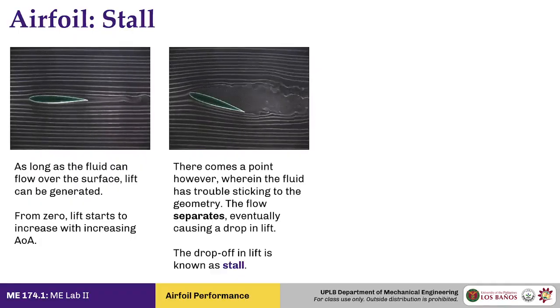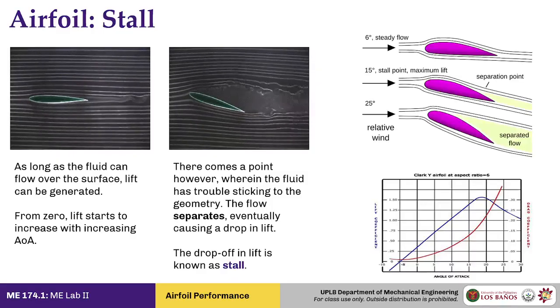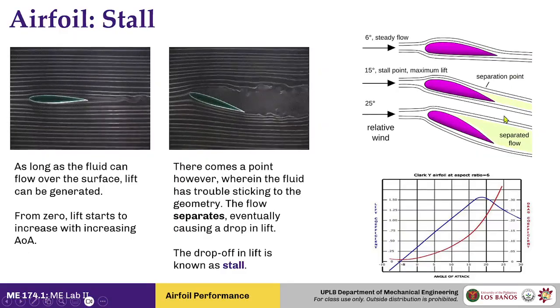Now, this situation that you typically want to avoid, that is why there is a lot of testing involved in the type of airfoil that you're using for aircraft. Now, if you look at this additional image, you'd see here three angles of attack for this particular airfoil. So when you have a low angle of attack, you have your fluid flow over most of the surface. For the stall portion, 25 degrees, there is a lot of flow separation. So the only part of the airfoil engaged in lift generation is this part, the leading edge.